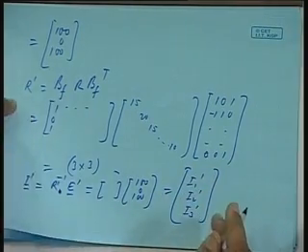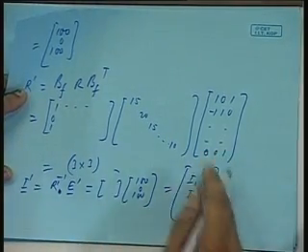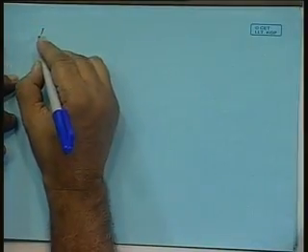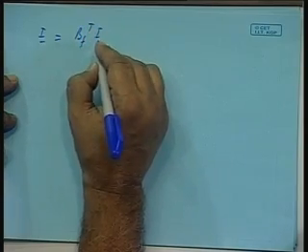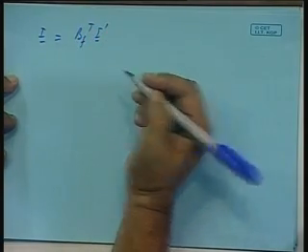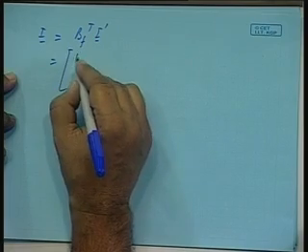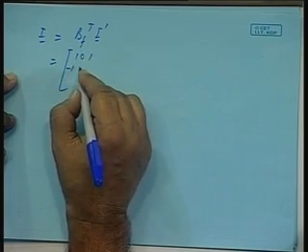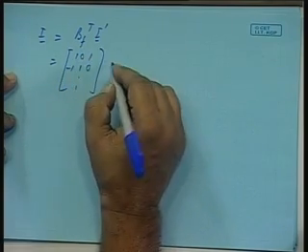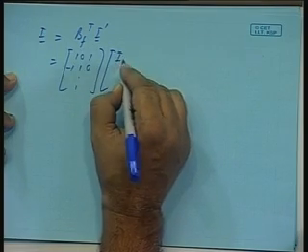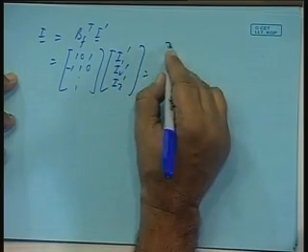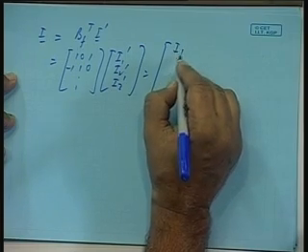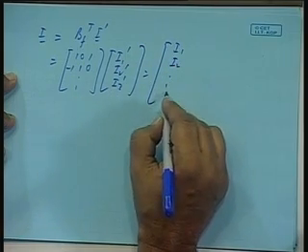Once you have got this, compute vector I, that is BF transpose into I dashed, and BF transpose is known, 1 0 1, minus 1 1 0 and so on, multiplied by I1 dashed, I2 dashed, I3 dashed. So, you get 6 values I1, I2 and so on up to I6.